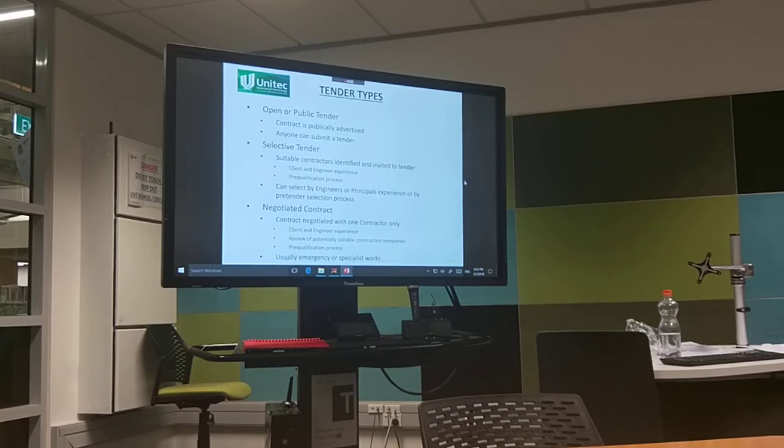How long would it take you to negotiate something as opposed to tendering? So tendering takes 3, 4, 5, 6 weeks. How long would a negotiation take? A week or two at the most. Okay, so the reason why you'd use a negotiated contract is because you want it done quickly.